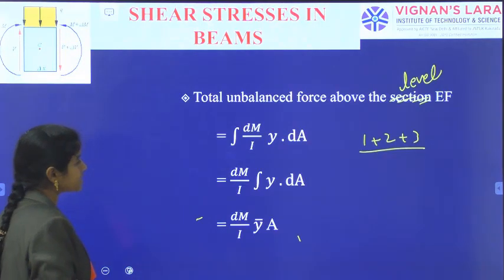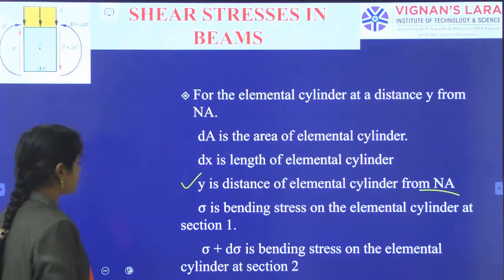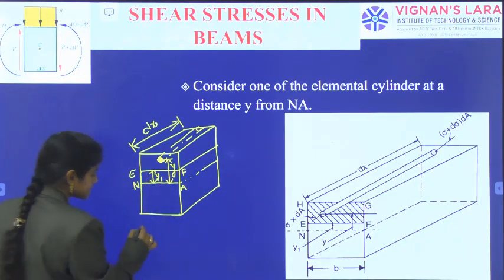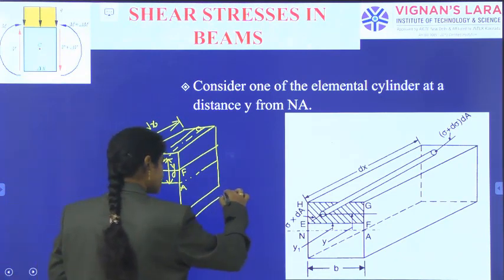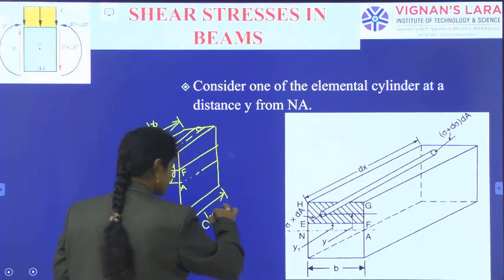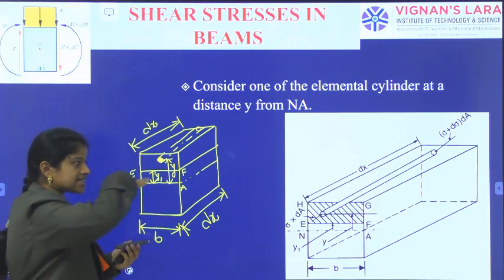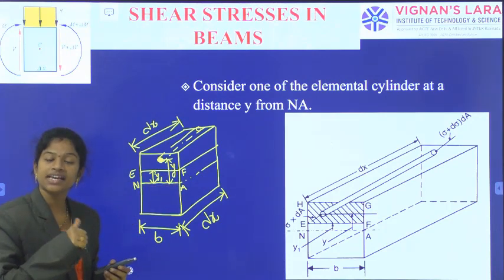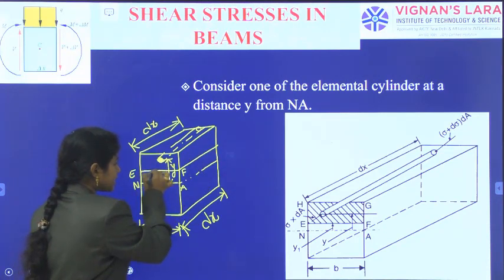As we have already said, this is our portion, right? This is the width of the segment and this is the length of the segment. And we said there is some shearing happening. So the net shearing stress is along this plane, and the shearing plane's area on which the stress is passing is B into dx. So on this area the shearing force will act, right?